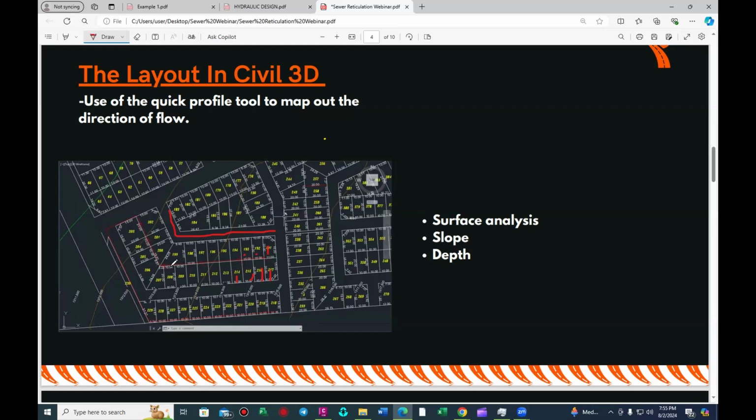If we lay our sewer line in between those stands, that enables us to service this batch of stands and that batch of stands at the same time. It's much more economic for us to do it this way. Someone would say, okay, fine, Byron, what if I lay my sewer in front of my housing stands? Suppose you want to lay your sewer like that. It's still fine, but you are only servicing these stands. You are not servicing those stands, you understand? So you need to also put another sewer line this side to service those stands.